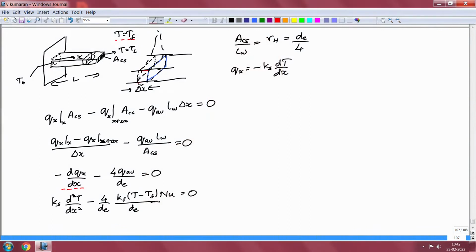So, in the previous lecture I was solving a problem of natural convection from a fin. A fin is often attached to the wall of a heat exchanger, and the wall of the heat exchanger is at some temperature T naught and the fluid is at some ambient temperature T f. The fin has very high thermal conductivity, and therefore the temperature at the surface of the fin does not vary very much with downstream distance, and therefore the fin is hotter, and because of that you get a much higher surface area for heat transfer along this fin.